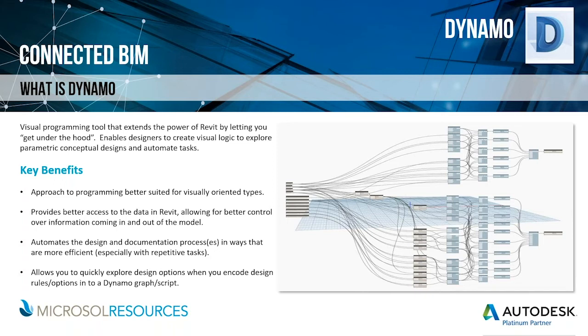Revit has certainly improved, but it can fall short with some of the more complex data-specific tasks that we want to do, namely with scheduling and the like. Dynamo can make this process easier. For example, we can use graphs to export data to Excel, modify that information in Excel as needed, and then use another graph to import that data back into the Revit model.